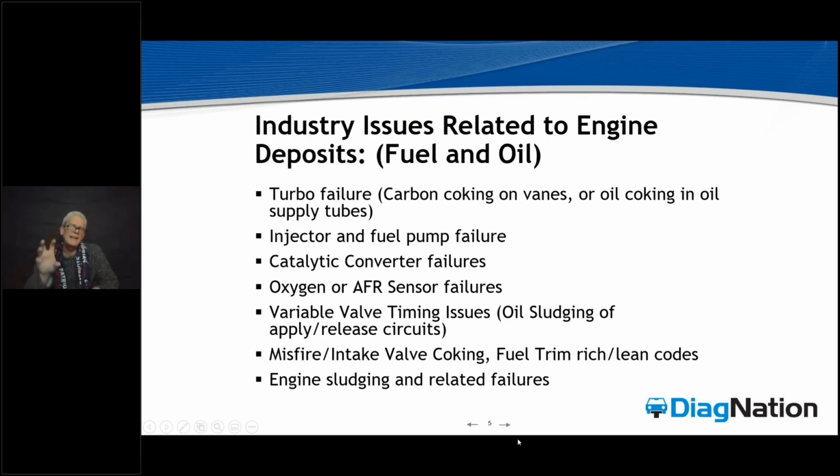Now, if we take that baselining thought process and roll it into the industry issues that we're seeing directly related to these carbonaceous and oil deposits, and believe me, guys, in the GDI realm, the oil control via the piston rings becomes a far more important argument as the start and the rapid degradation of the engine occurs based on carbon loading. It all starts with the rings in a GDI car.